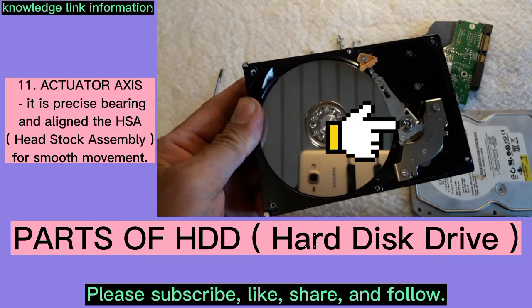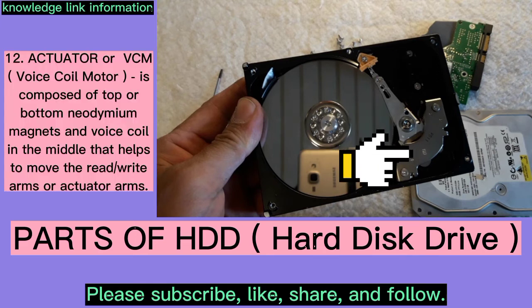Number 11. Actuator axis. It is a precise bearing and aligns the HSA, or head stack assembly, for smooth movement. Number 12. Actuator, or VCM, or voice coil motor, is composed of top and bottom neodymium magnets and a voice coil in the middle that helps to move the read and write arms, or actuator arms.